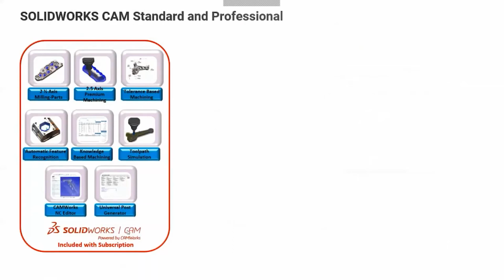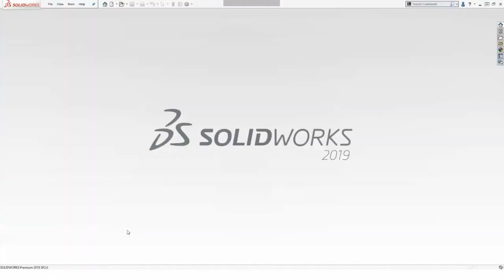To get to SOLIDWORKS CAM, if you've never done it before and didn't know, I'm just going to go ahead and show you. I want you to go right to your Tools tab right here. Find your add-ins.